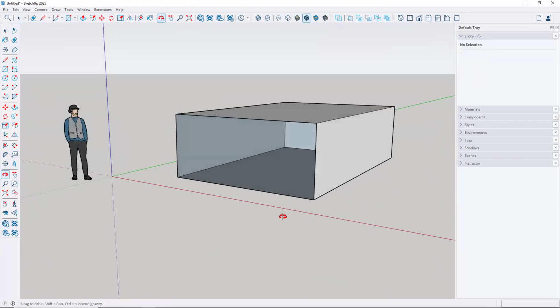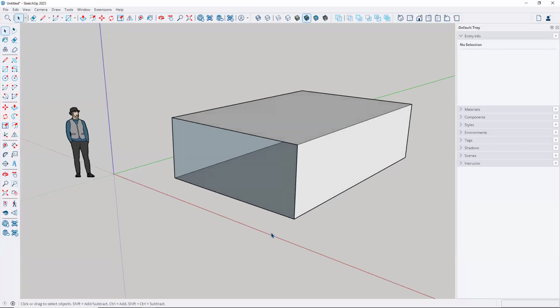All right, so now on the inside, there's the space, but I want to cover it back up. So to do that in SketchUp, it's really nice. I can go ahead and type L for the line command, and I click on any endpoint, and then I'll pick another endpoint. And as soon as I do that, SketchUp detects that there were already other edges there, so it's just closing it up. And then I'll tap the escape key, and then I'll tap the space bar, just in case I was in the middle of drawing a line. So space bar takes me right back.